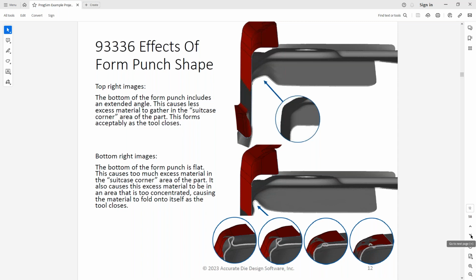There's a part where you can kind of see the X-ray through your tooling. You can actually stop a quarter inch before the tool closes, and see the overlap starting to happen. And you can start to see that if we hit this leg a little earlier, then that wrinkle wouldn't be happening out there. In real life, you can only see the closed or the open state of the press, so it goes from one state to the next, and there's just a jump. You don't really see how exactly the material flowed, so being able to actually see the movements happen here is really eye-opening on some parts.